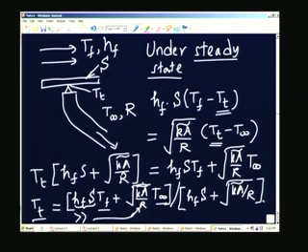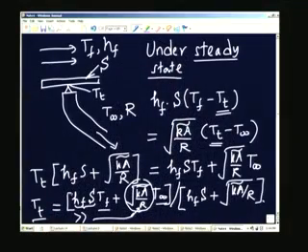That means, that if I am able to reduce this factor by the proper choice of the insulating material and so on, and also making sure that there is not too much of convection at the back side, and if I make sure that this product of Hf into S, if H is not very large, if I make S large enough, then this product becomes large enough. Therefore, the idea is to increase the product of the heat transfer coefficient on the fluid side and the area of contact between the fluid and the solid. If I increase it, then Tt will approach Tf.